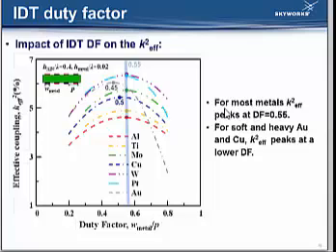This is because gold and copper are relatively soft and heavy, which means they destroy the wave concentration from the piezo film and destroy the wave shape more than the other metals, in spite of the enhanced reflection.